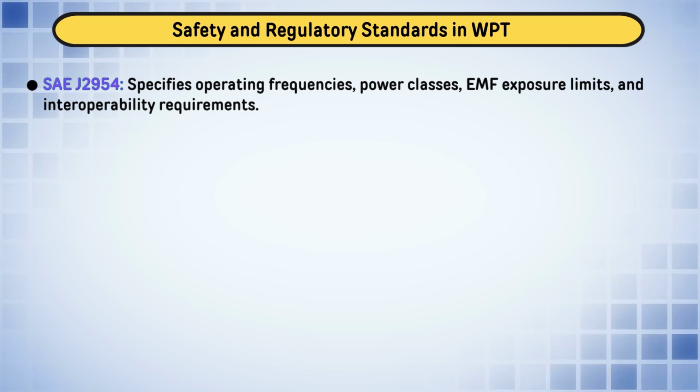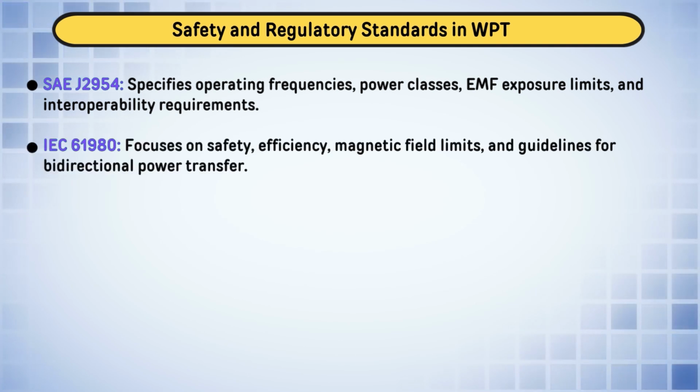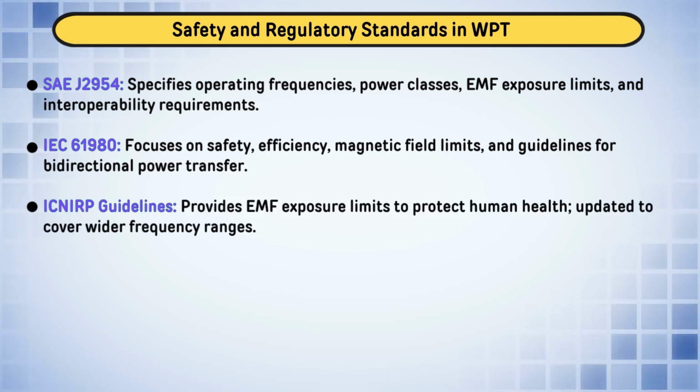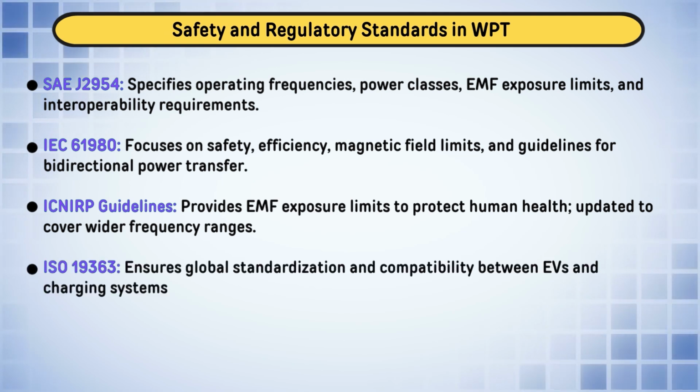Then we have the battery charging control. Similarly, we have switched this converter depending on the SOC of the battery in CC and CV mode. The same control is utilized for this purpose, and here we have some waveforms from the primary and secondary side. On the primary side, as we have used a DAB converter, it is a square wave, however, the secondary side voltage is realized as a quasi square voltage because we have utilized the 3 leg converter.